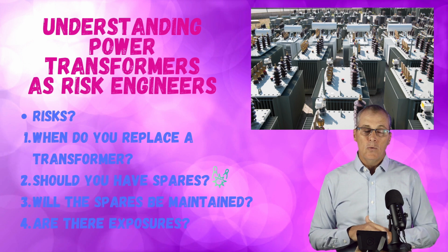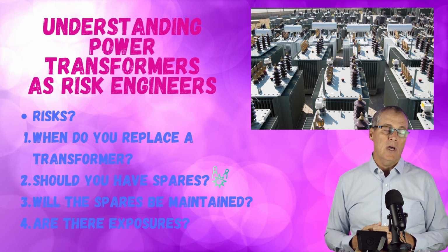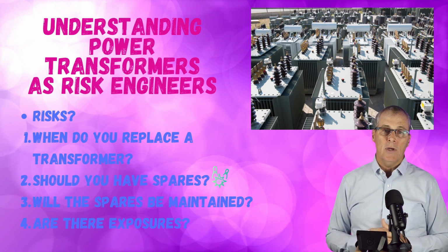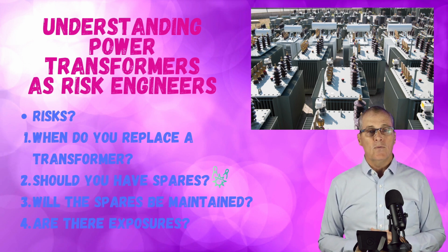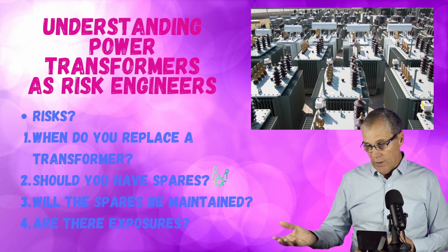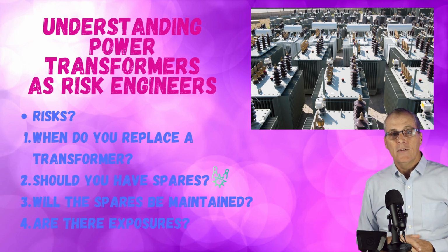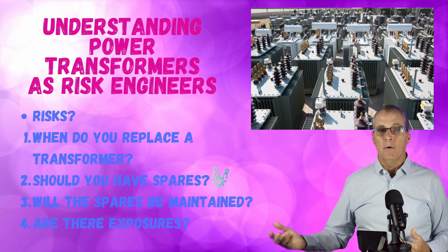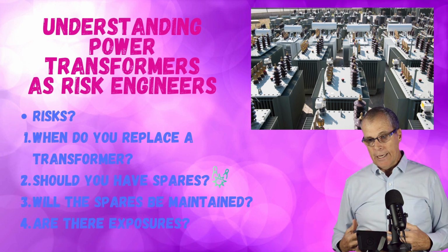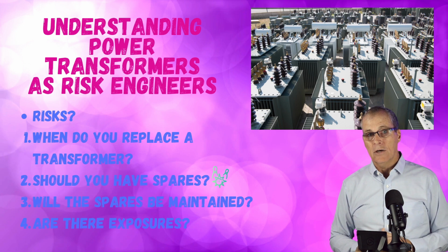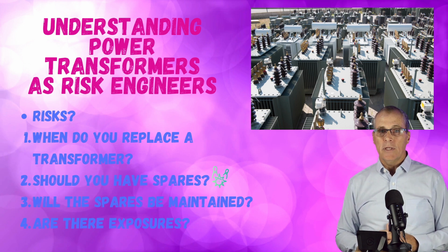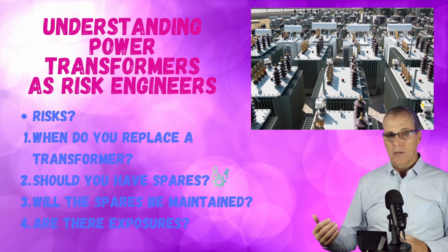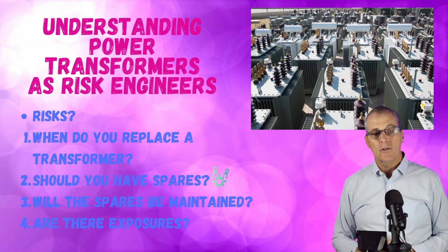Let me say that if you have spare transformers, they need to be maintained. We've also had clients that had spare transformers and, within basically days of installing the spare transformer, it fails. So it's really important that the spares are maintained equally as vigorously as the main operational units are.